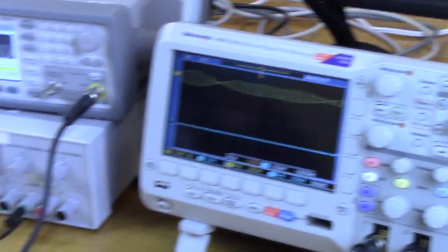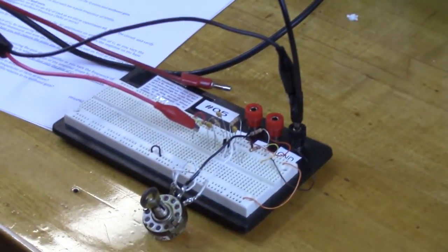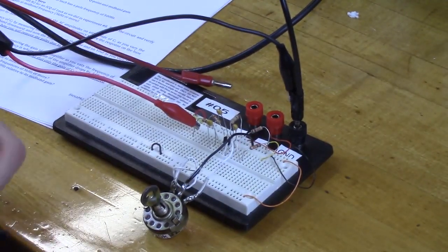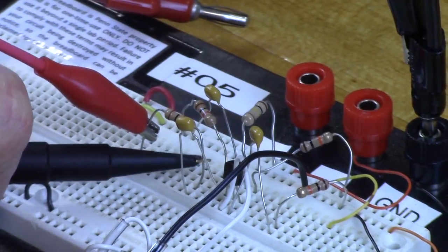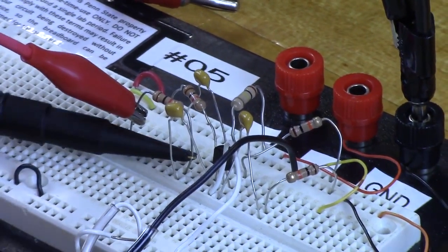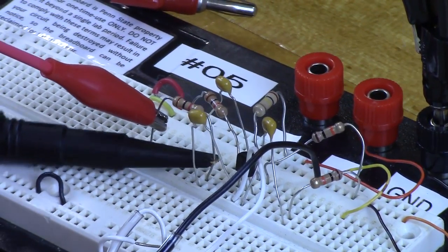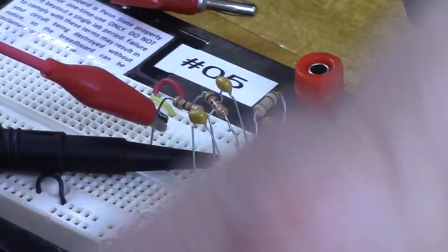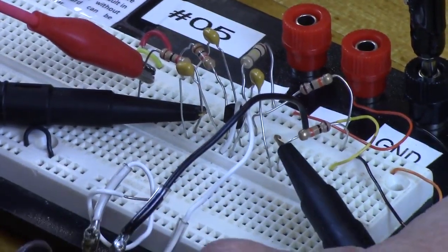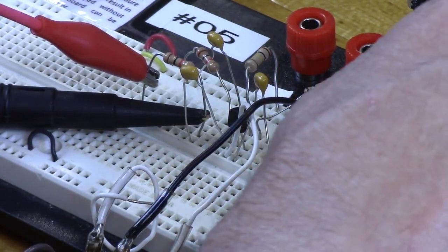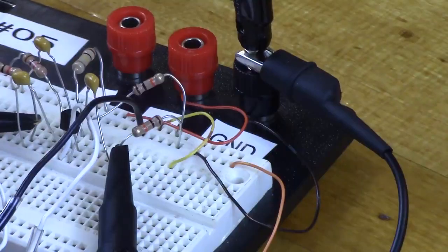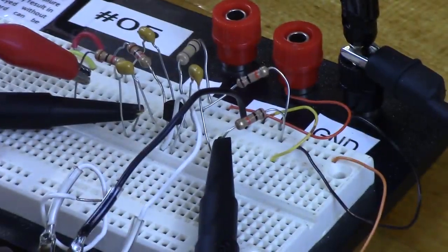Okay, and we're going to connect channel 1 to the right side of RS. The yellow one goes to the right side of RS. I like to clip it onto the resistor because it's a thicker wire. It's just more solid when you grab hold of it. And the output is going to be across RL, which is all the way over to the right here. And let us ground the scope probe over to there. So at this point, we should be ready.